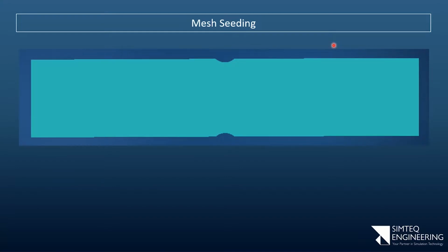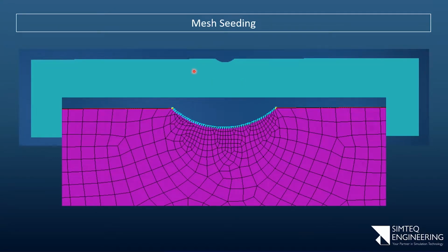So here's a simple example. A test specimen with notches cut out. And in this region, if I apply a tensile load, I expect the maximum stresses to occur here. So if I use a mesh seed, in this case, say 0.5 millimeter elements here, and 2 millimeters here, I specify that on both of these curves, and then I mesh.